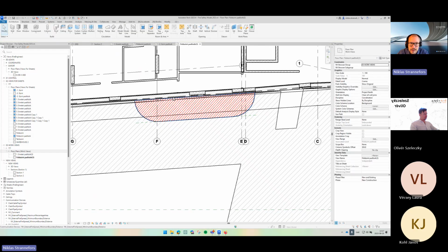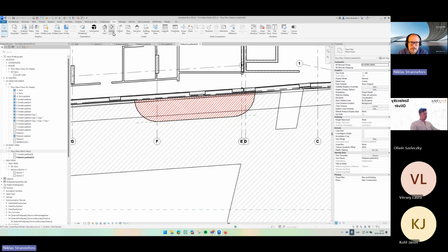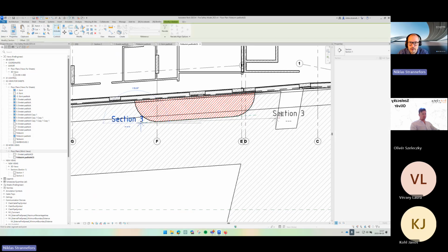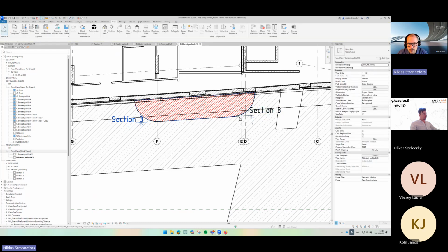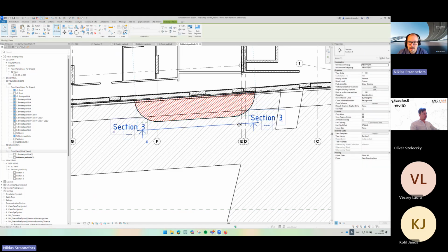While we're doing the ref planes, we can actually snap a section to the endpoints and then move it backwards. Because we can snap sections to reference planes, and then we can pull it back as long as we're perpendicular with the symbol.